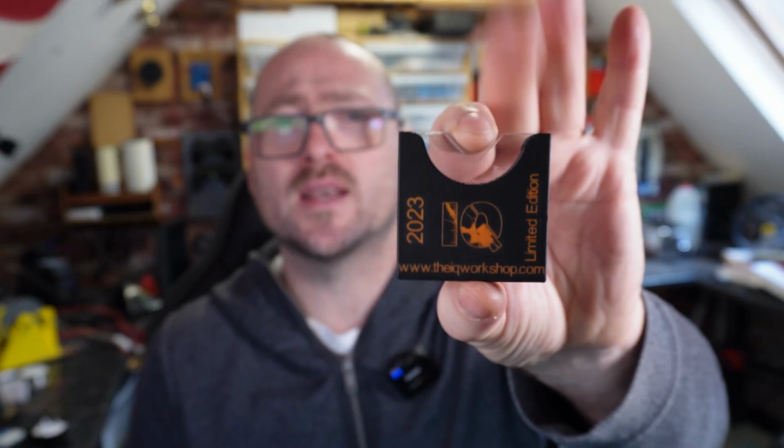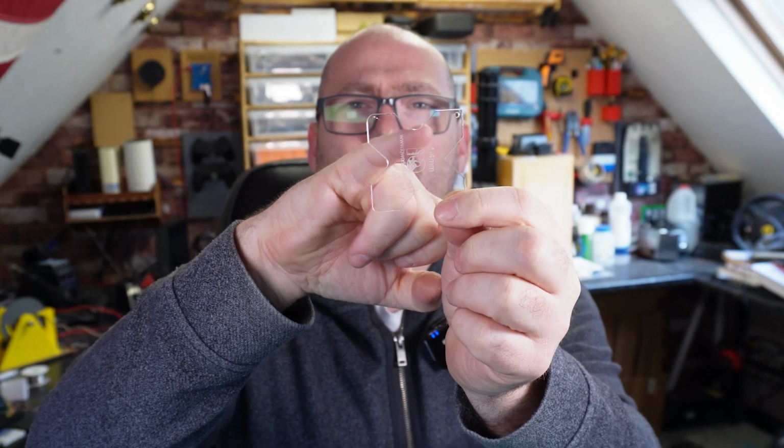Next up, we've got some radiuses on these edges. One of the things that I made was a set of radius finders. Essentially these are like feeler gauges, I suppose. Each of the external corners has a particular radius, and each of the internal corners has a particular radius. I can offer this up to an edge, either inside a box, if I'm trying to get the inside radius of a box, for example, or if I want to offer it to the outside radius, I can quickly find the radius with these radius finders and enter that information directly into the sketch.